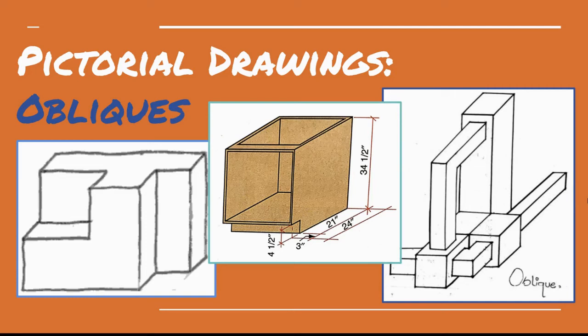In this lesson, we're going to see a type of technical drawing called an oblique. Obliques are similar to other pictorial drawings in that they show us three sides of an object in one view, giving us a 3D effect, but they have some characteristics that make them a little different from other pictorials.